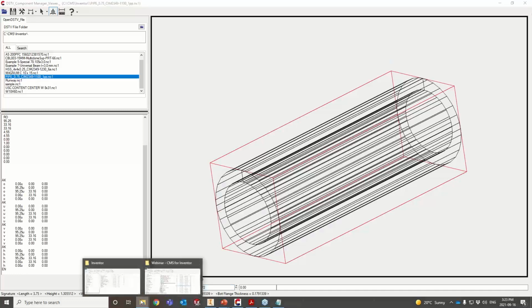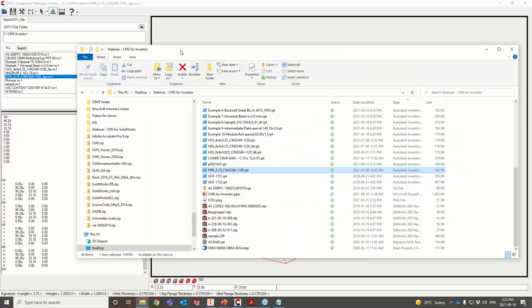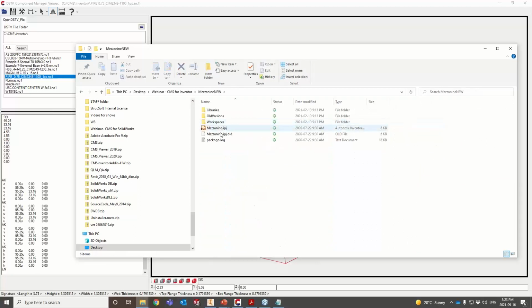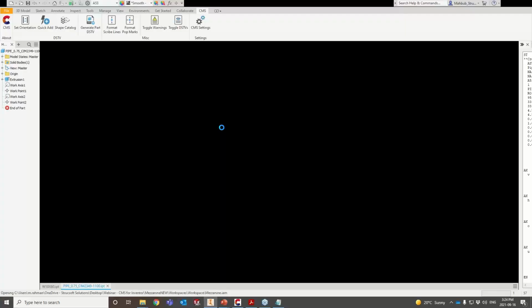Well, I'm just trying to find an example, but I'll just take the example that I worked with. So what you have to do is open your sub-assemblies actually. You cannot work on your sub-assembly directly from your assemblies. So you have to open those sub-assemblies and work from there, just like a regular assembly. So unfortunately, you have to go to your sub-assembly level.